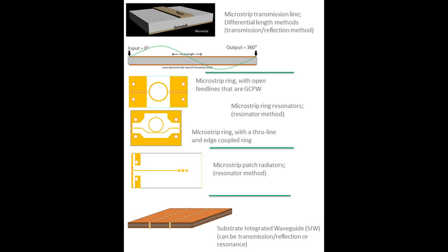Now the ring resonator below that is a little different concept, and I actually like this more because this structure is less affected by normal circuit fabrication variables. It is basically a transmission line with a ring resonator set right next to it. So you have a transmission line, and what you would get would be a normal insertion loss curve of a transmission line, except where that ring that's edge coupled to it resonates.